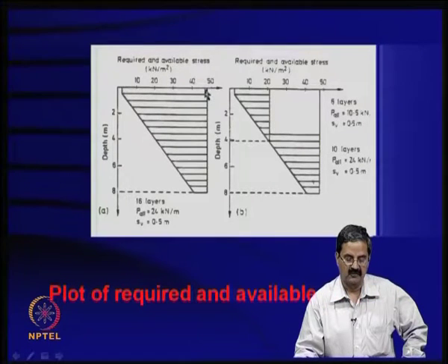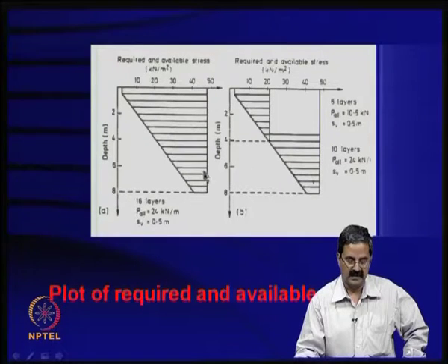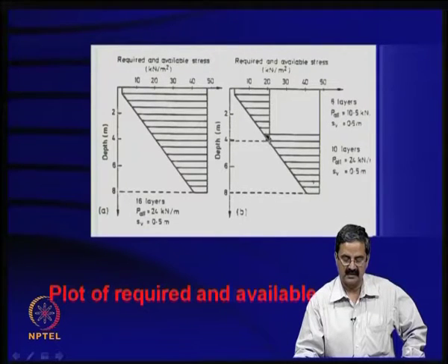You can see that 48 kilonewtons is available. Maybe it is fine here up to some level, but you can see that it is all wasted here. If you use a very good material with 24 kilonewtons, it is not worth having 16 layers, it is underutilized. So, one way is that you take the 10.5 kilonewton one and then have spacing, and you can put up to some layers wherever it comes in.